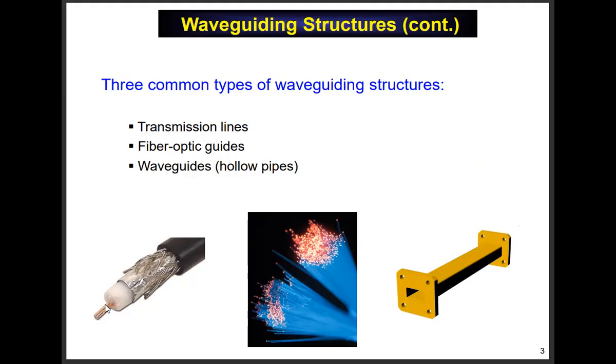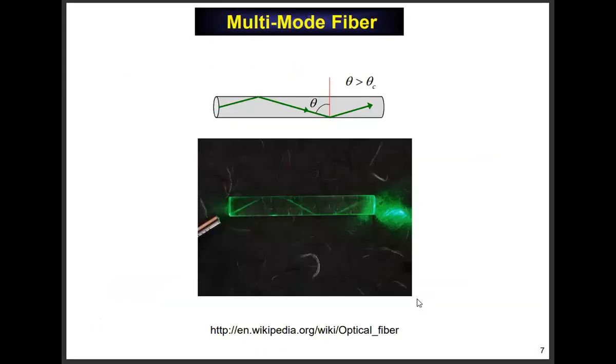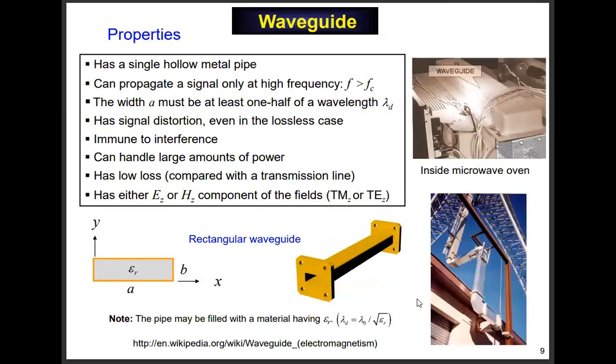Surface current is what really gives you loss because of that effect called surface resistance that we talked about, the RS. But if you can spread out the field as evenly as possible here, then that means that surface current density is more uniform around the boundary and not so concentrated in one area, and that's good for lowering the loss. So distributing the fields throughout this cross-section allows you to transmit more power for a breakdown, and it also says it's going to be lower loss, less dB per meter. And that's good for high-power radar applications. You don't want to waste power, right? You want all the power to go through, and you don't want dielectric breakdown.